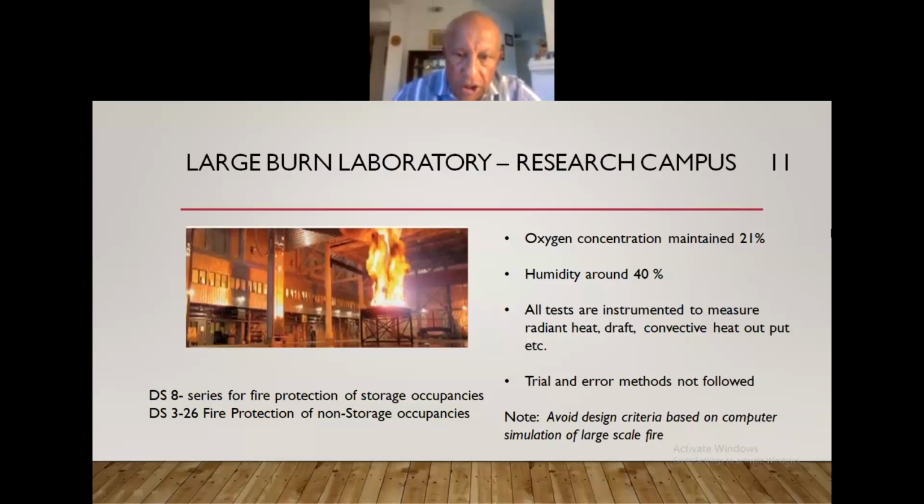Okay, one word of caution: when you are doing your design, particularly fire protection, if a consultant walks in with a computer model and says, "This is too expensive, so I have done a computer model to come up with a protection criteria for a 40 feet high plastics commodity storage fire," run from him like the plague, because FM Global, with 187 years of experience and a 300% computer science laboratory, have not been able to do this so far. Down the road, they may, but not yet.